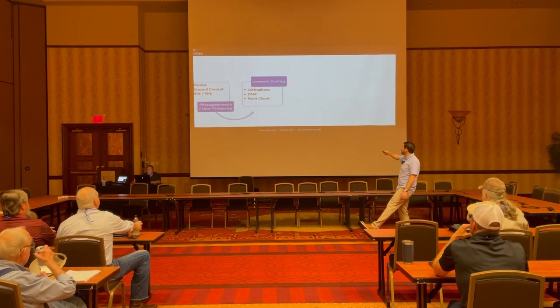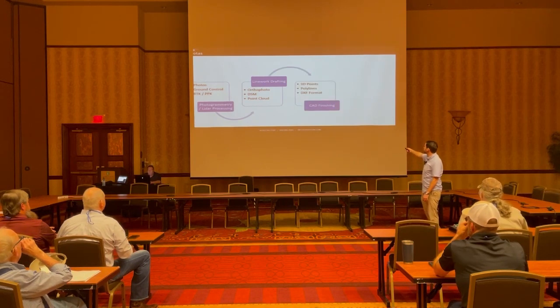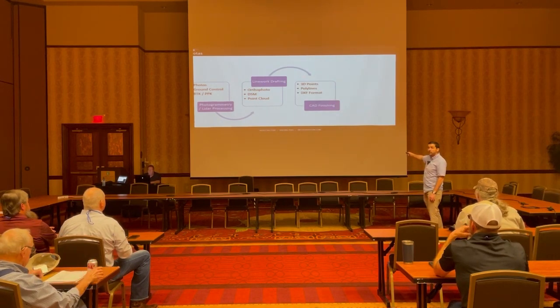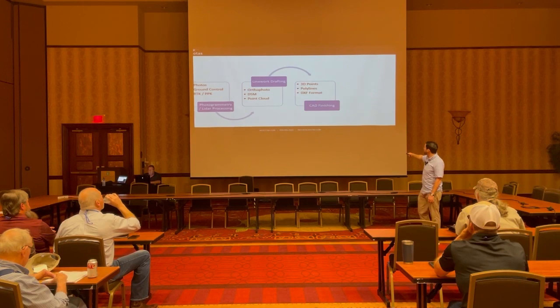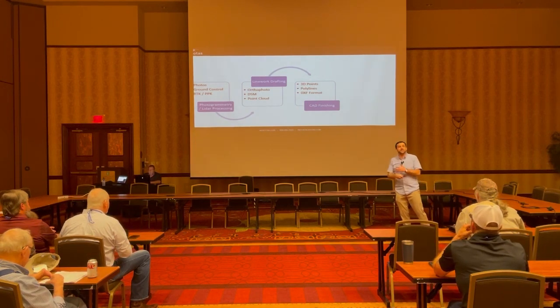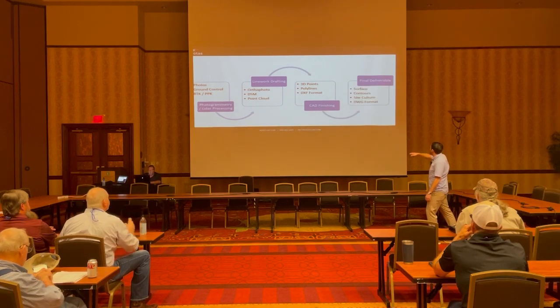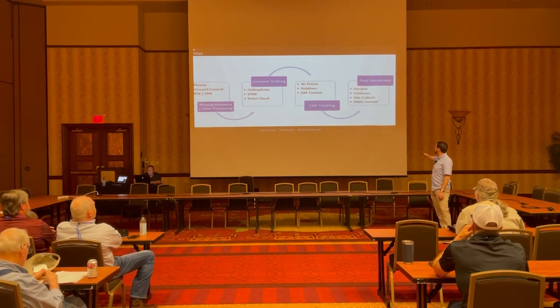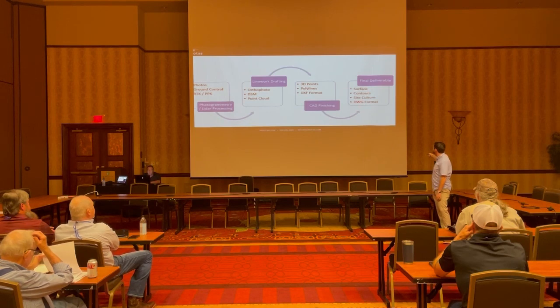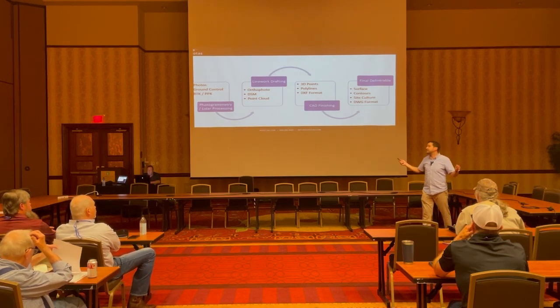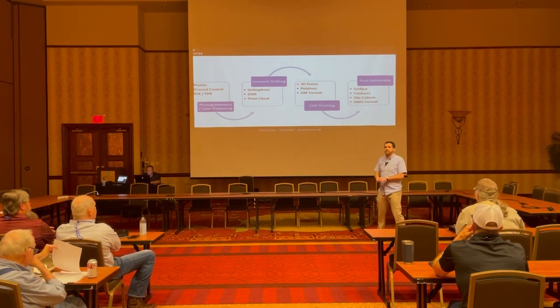You run that through the line work drafting step, which will spit out things like 3D points that you've extracted, maybe some polylines, typically in a DXF style file format. Run that through the CAD finishing step, and that will get you your final deliverable, including a tin surface, contours, site culture, things like street names, for example, in your DWG format.